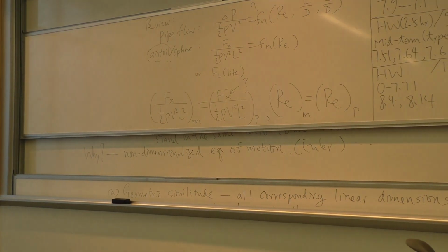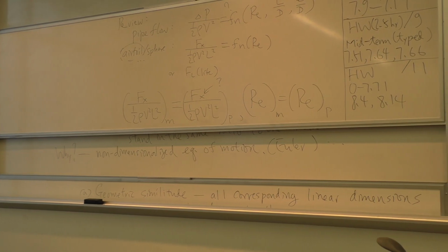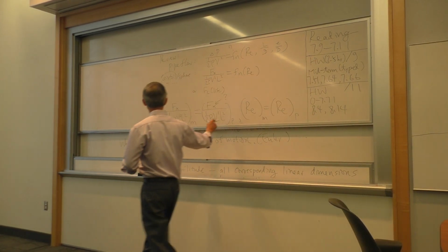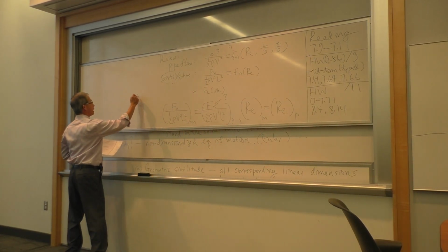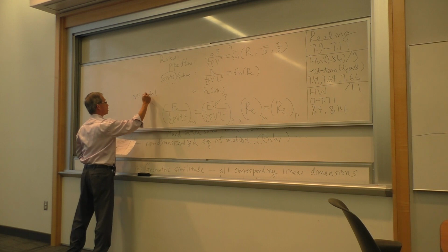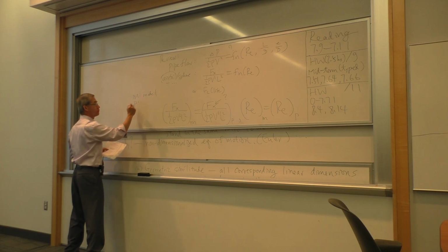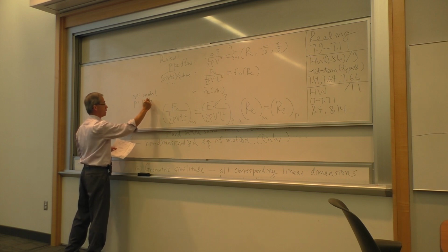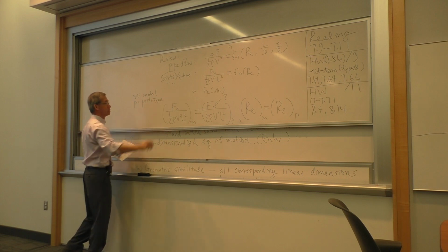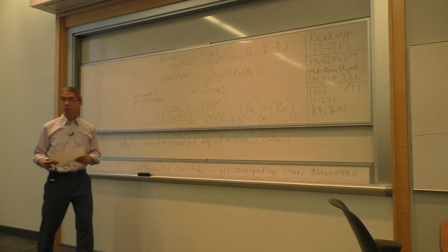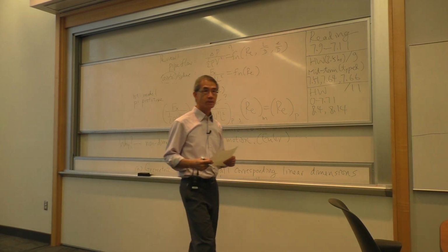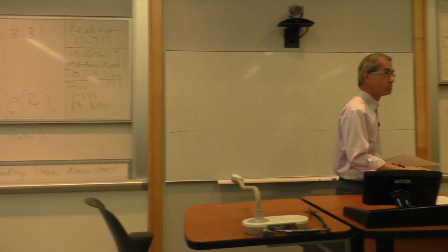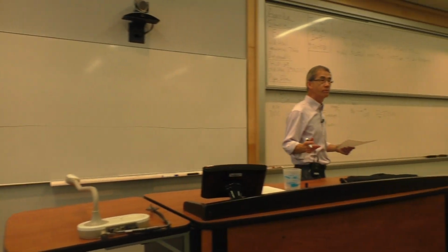So what are the M and P subscripts again? Sure. Good clarification. All the subscripts I use now, M stands for model, P stands for, anyone? Prototype. Yeah, that's the same nomenclature we'll use throughout the semester. Right, so I don't care if it's air versus water, as long as the Reynolds number is matched, I have the same physics. The flow will behave exactly the same.